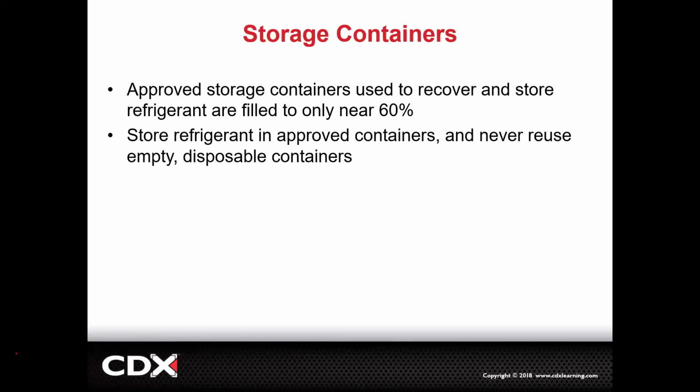But the other thing is refrigerant that you buy at the store. Let's say you have our machine, or you buy gauges and you want to just do manifold charging, you can. If you go and buy the refrigerant to charge it, that's going to be disposable. So the disposable container is not made for recovering.